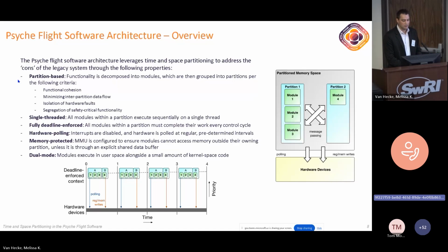We also leverage our MMU so that partitions cannot corrupt each other's memory space. And we have a concept of dual mode execution, meaning that most of the flight software runs in user mode, and we have a small amount of support code running in kernel mode.